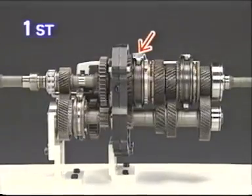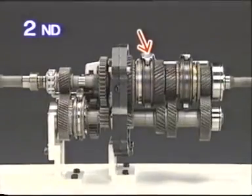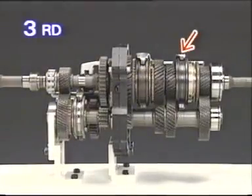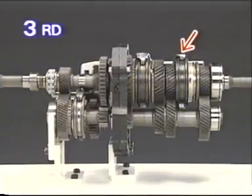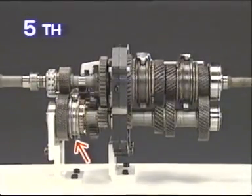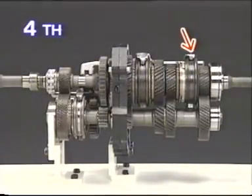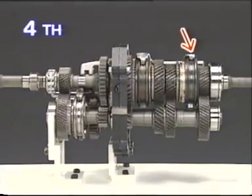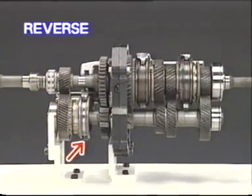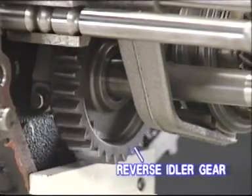From the first to the fifth gear, except the fourth, power is transmitted along the input shaft, main drive gear, counter gear, respective gears, clutch hub sleeve, and output shaft. In the fourth gear, the input shaft and output shaft are directly connected. In the reverse gear, the idler gear is added. This gear makes the rotational direction of the input shaft opposite to that of the output shaft.